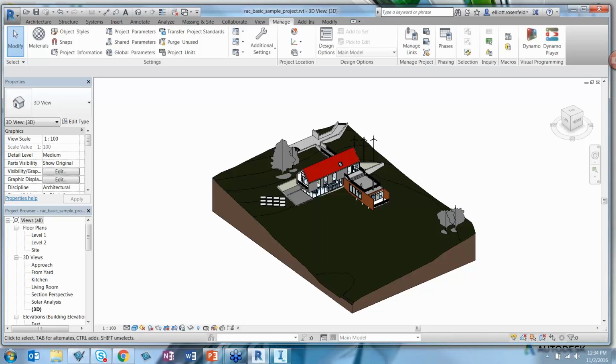And also one thing I always forget to mention, linked files. If you have linked files, which is basically an XREF in Revit, those will not come through. It has to be live in your Revit model to come in.